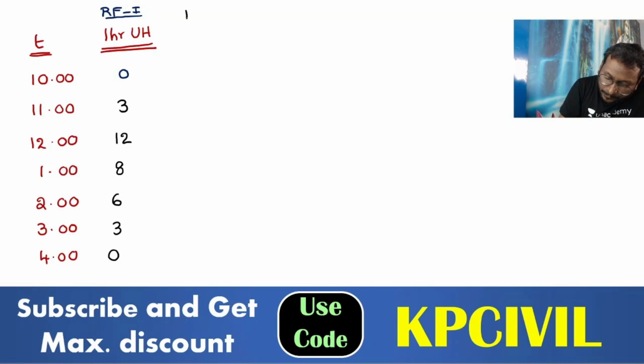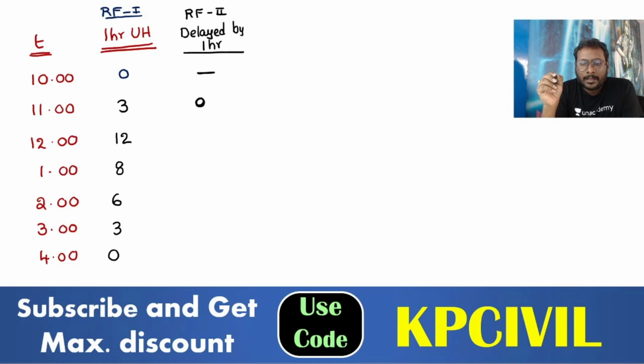Now I am writing rainfall 2, 1 hour unit hydrograph ordinates. When did rainfall 2 start? Delayed by 1 hour. It started at 11, so it does not carry a value at 11.